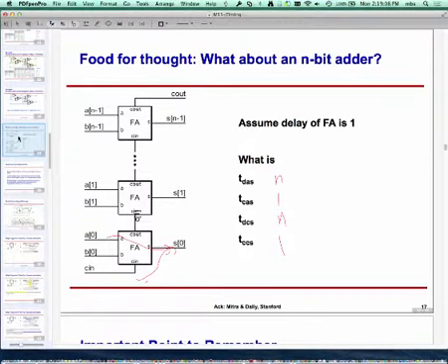It's the 12 that you are interested in, not the 10. So there's a band which is always given. Again, the two values of interest in design are contamination delay and propagation delay. Minimum delay is an ambiguous term, just stay away from it.